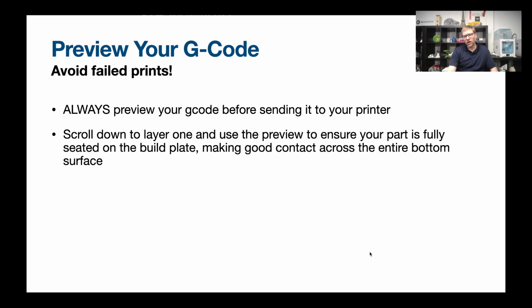And then a really important tip, that if you take nothing else away from this session today but this, it will have been time well spent. Always preview your G-code before sending it to the printer. Nothing's going to save you more time and more frustrations than this. And preview it in a specific way.